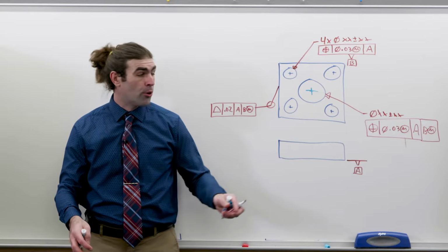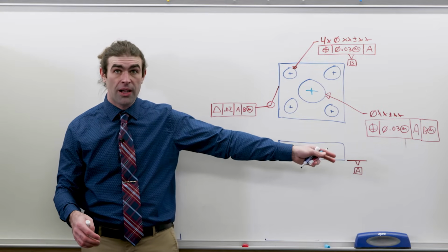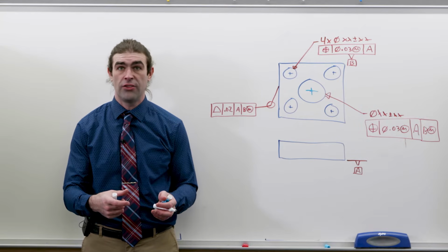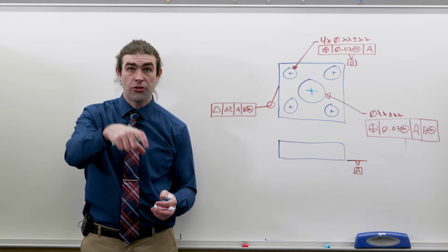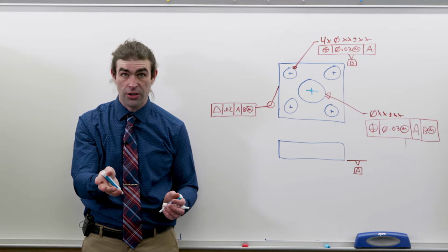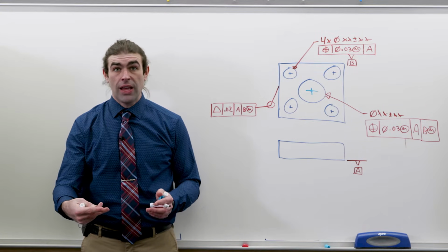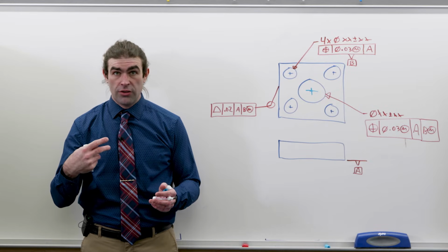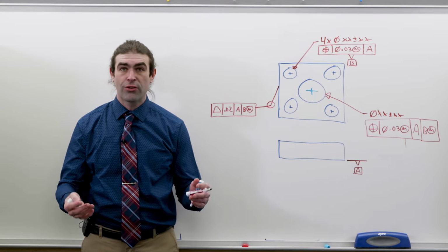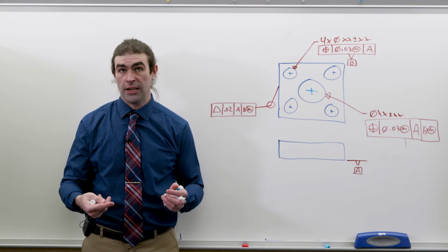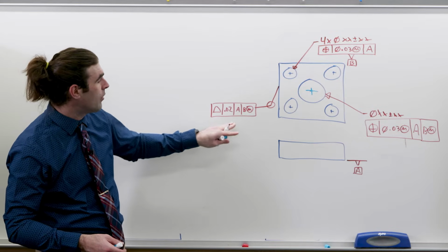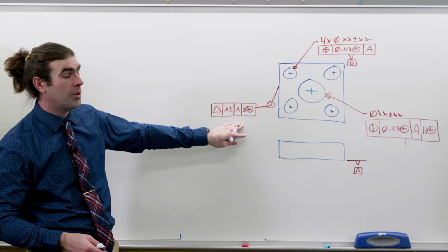But if at all possible, if you can use the MMC modifier, it's possible that you could have fixed gauging for that. So you could have a robot drop the plate on 4 pins. If it fits, it could check the next thing, you're good to go. At worst case, you could check it with a CMM machine, and the MMC just gives you extra datum shift if you need it. So this outside right here has a profile to the same datums, A, B, and MMC.